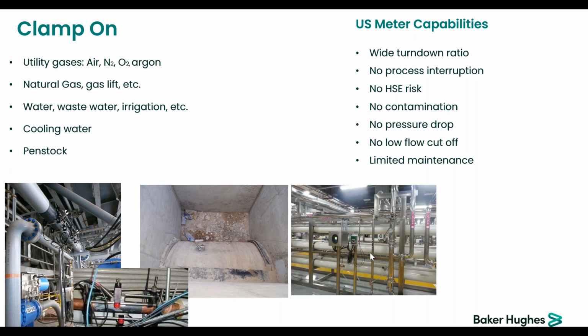The one that you see there, I cannot say the brand, but it's an electronics producer. So all the lines are stainless steel because it's kind of a clean room, and you can see that one of the lines is CIP, clean in place, which means that even if in normal operations the temperature at the transducers is not very high, during the cleaning in place it goes up, but the transducer can withstand those high temperatures without the need of being removed. So it's also an advantage.